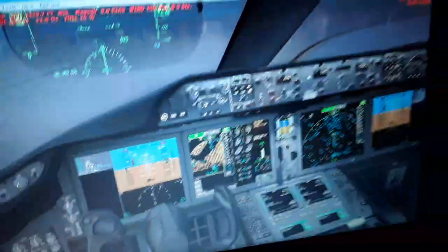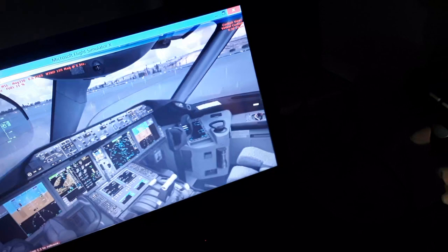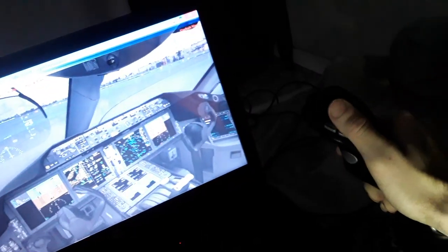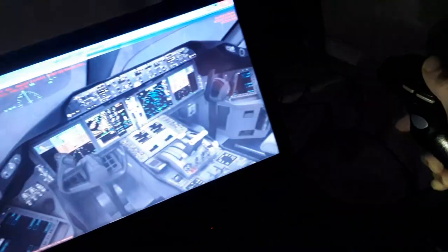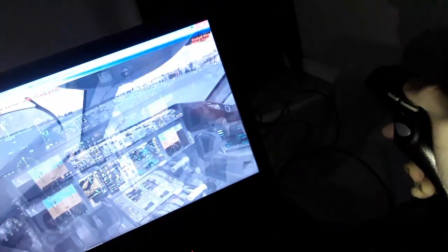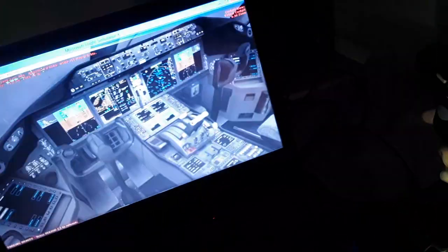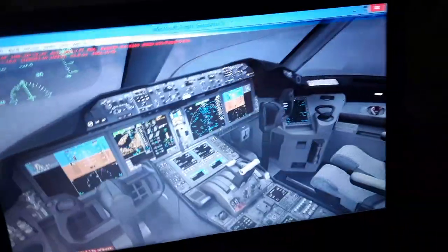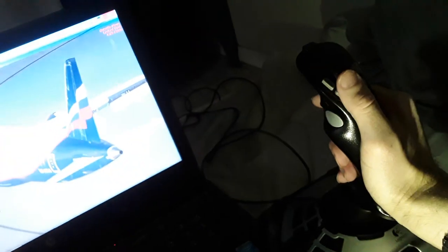So when in flight, you move the flight control of the aircraft, like the yoke for climb and descent, to deflect the elevator. On spoilers, you give a command to the flight control computers to make calculations about the flight control deflections, or the rudder, like in the Airbus aircraft. Also, you have the automatic trimming. So when you fly, you move the side stick in the Airbus for climb and descent. On the Boeing, you move the yoke, you move the elevator, climb and descent.